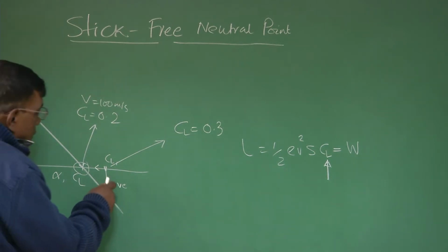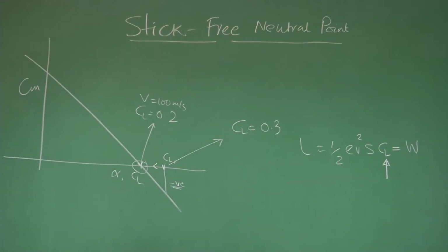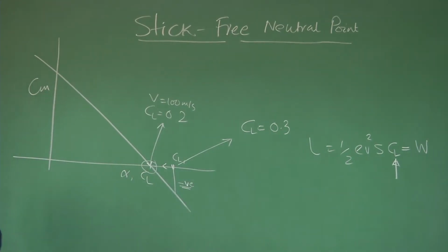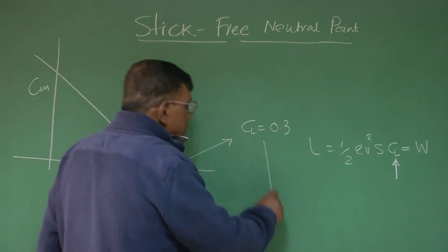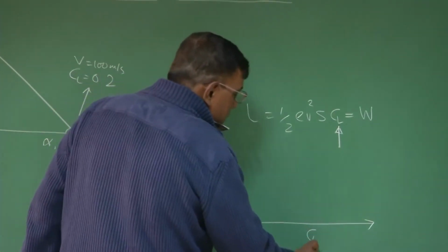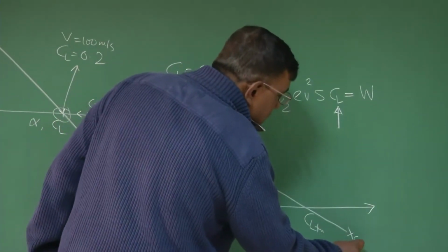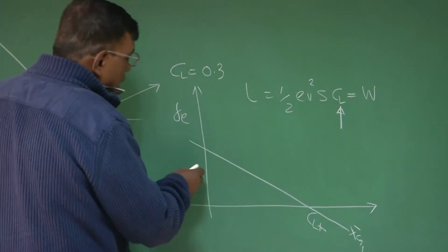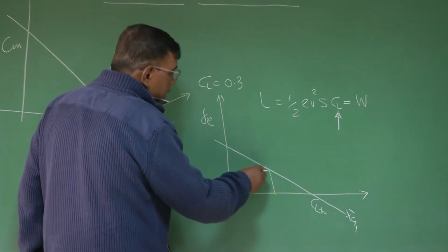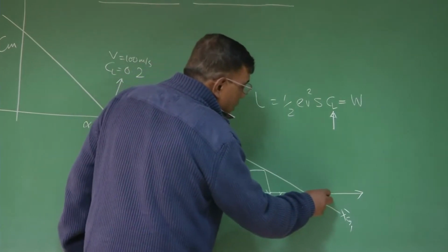And you also know that if I want to fly at this CL1, it will generate a negative moment. So, I have to generate a positive moment by giving elevator deflection, right? And that is why, if you see this graph, delta E versus CL trim for a given CG location, XCG1, you have a definite value of elevator deflection required if you want to fly at this CL, at this CL, or at this CL.